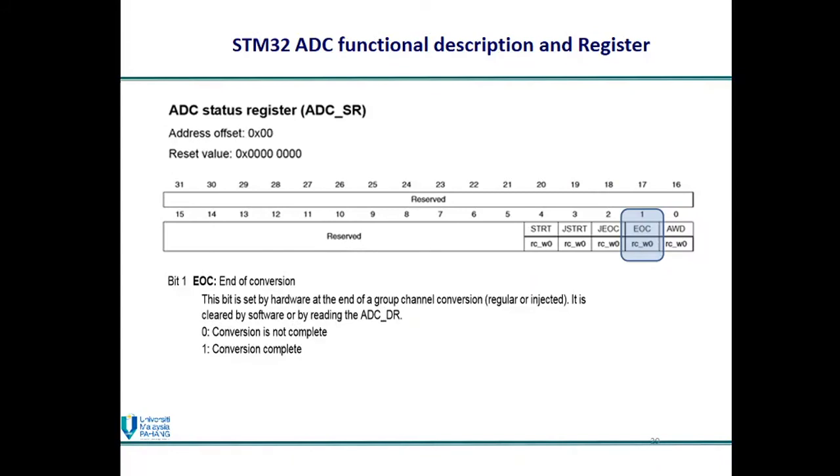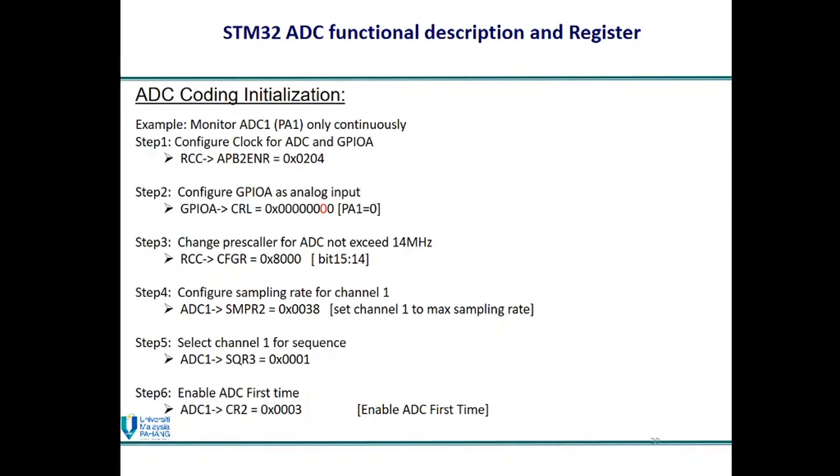Okay, the last register we need to monitor is the ADC status register. Bit 1 of this register is the EOC, end of conversion. So we need to monitor this bit to make sure the conversion is complete. Okay, that's all the registers and their function descriptions.